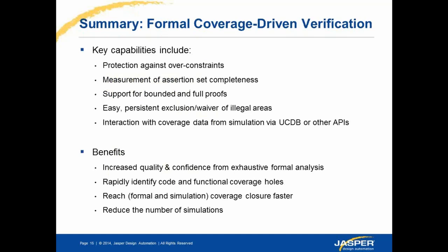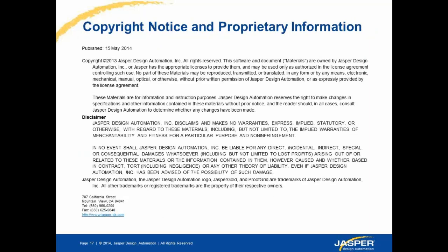Here is a brief summary of my presentation today. Using the coverage metrics designed for formal by Jasper, you can address the problem of property completeness, and you can also get visibility into the observability of your RTL vis-a-vis the assertions. You can use stimuli coverage to identify any potential over-constraining situations in your design. You can also use the coverage app to help you in the simulation coverage closure flow. And that's it. I'm done.